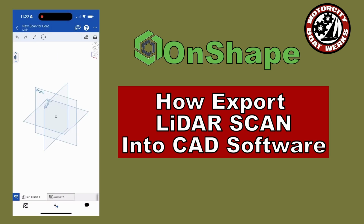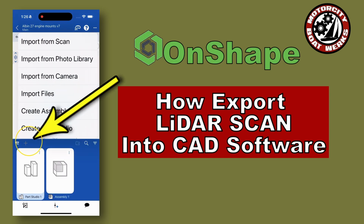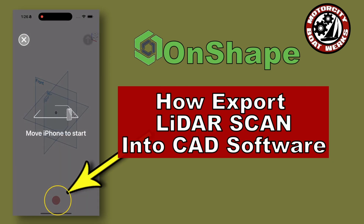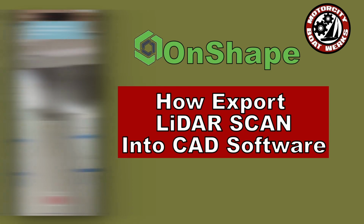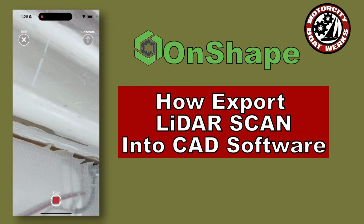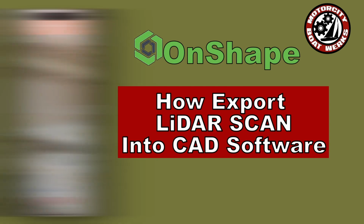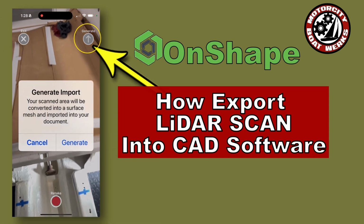Now we're going to make a scan. In the bottom left corner in the blue, it looks like a magnifying glass with a ruler. Click on that. You'll see this menu. Click on the first one, Import from Scan. This will access the LiDAR scanner in the phone. The scan won't start till you hit the record button. Now you can begin your scan. Follow the on-screen prompts, move slowly, try and fill in all of the scan area. Once you've got everything, go ahead and hit the stop button. In the upper right corner is a button that says generate. Click on that.